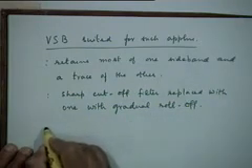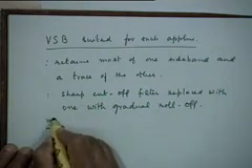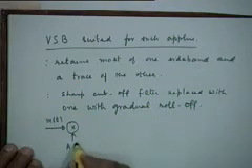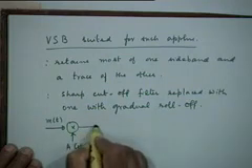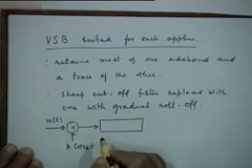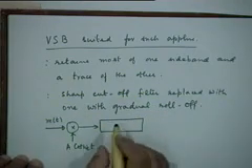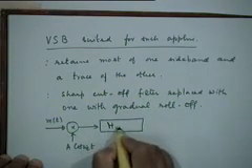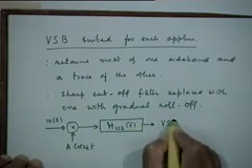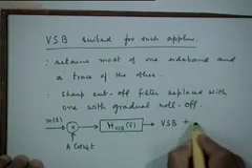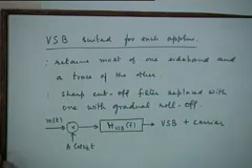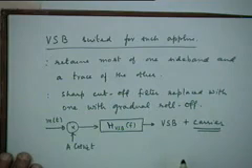So what we are saying can be pictorially expressed like this. You generate your message signal, you do DSB-SC modulation on this by multiplying this with A cosine omega_c t, and you have a sideband filter here, but it is not that sharp cutoff filter. We will call it some H sub VSB of f, which will yield the VSB signal. Typically, if required, it will also send some portion of the carrier, but that's not important right now. Right?